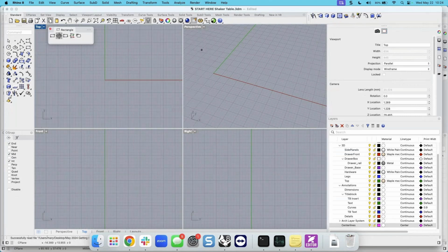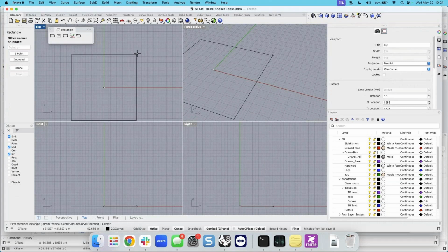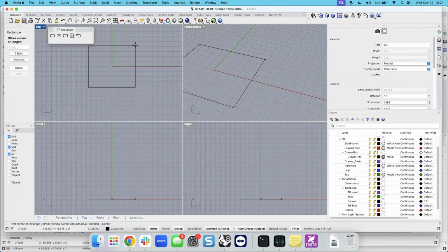Okay, here we go. Pick the centered rectangle. I could type in 0, 0, 0, but why? Because Rhino will just let me type in a 0 and an enter, and now I'm centered on the origin. And I prefer, if I'm modeling symmetrically, to use the origin because it helps me detect if I'm out of symmetry at any time. So that's why I'm at the origin.